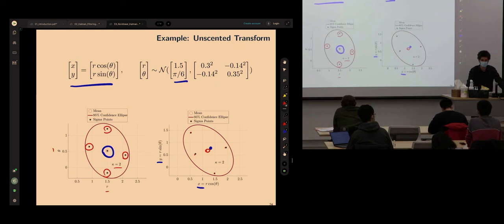So in EKF, we calculate with the estimate as a linear function. So you're saying instead of the nonlinear function, use the linearized version. So that's even worse. You're replacing the exact nonlinear process model using an approximation. At the very least, for the mean, we could use the exact process model, right?